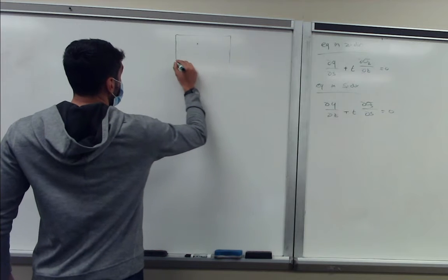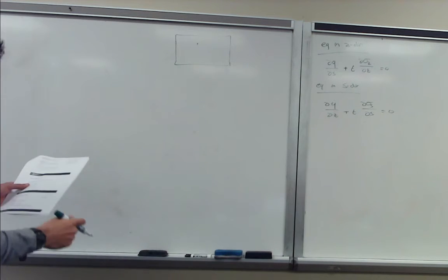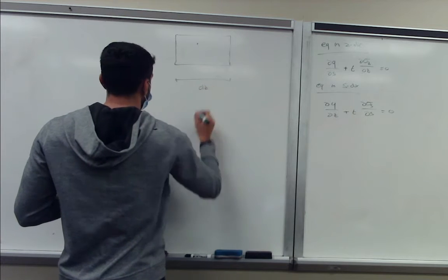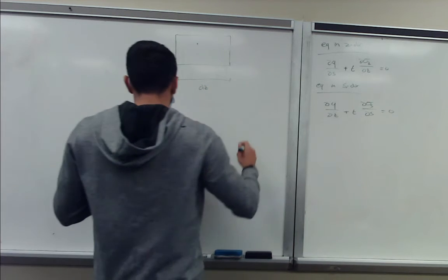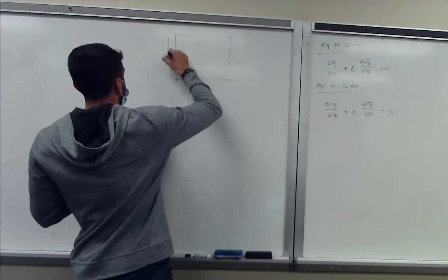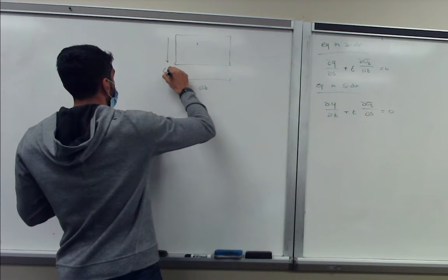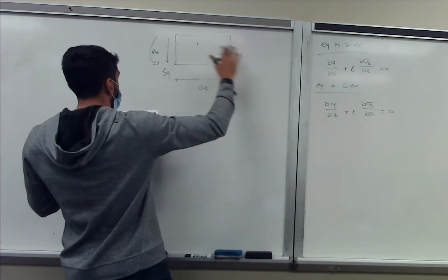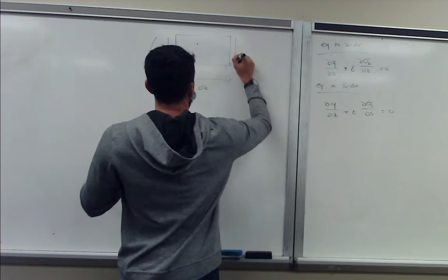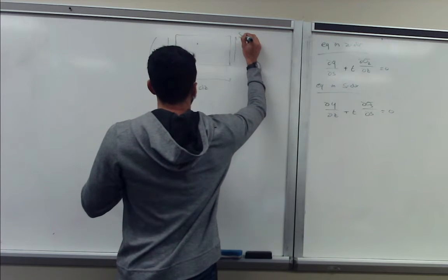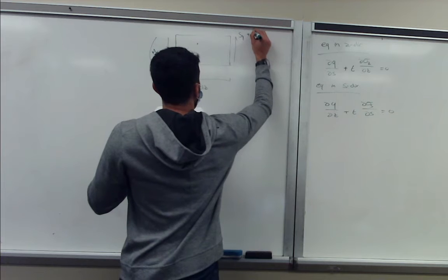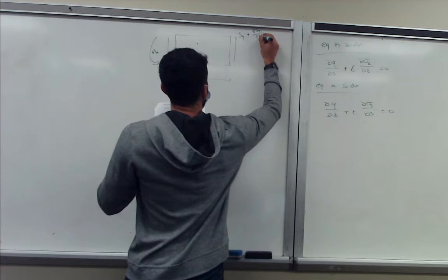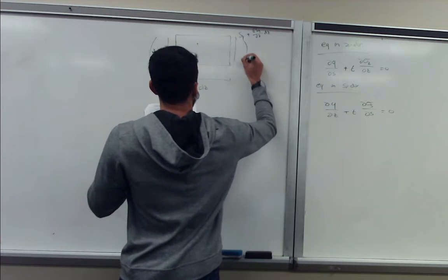We can define an element somewhere in our body, with a certain delta z or dz. We can have a shear force Sy applied, and a moment around x, Mx. And to be in equilibrium on this side, we must have Sy plus the variation of Sy with respect to z, dz.